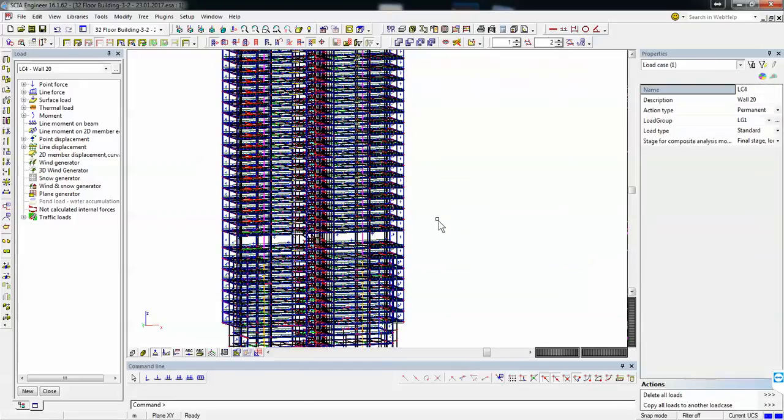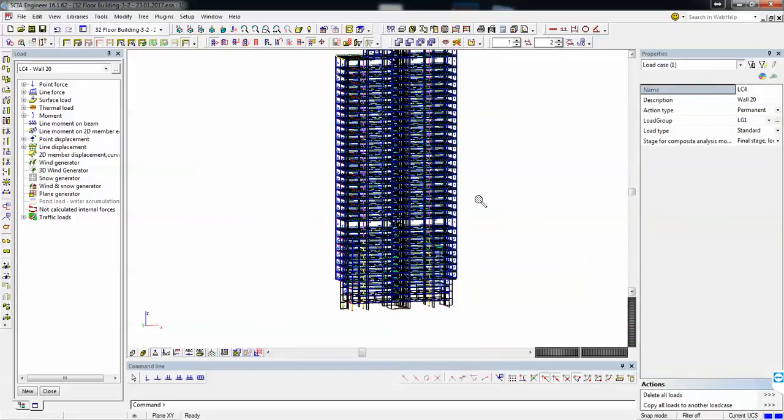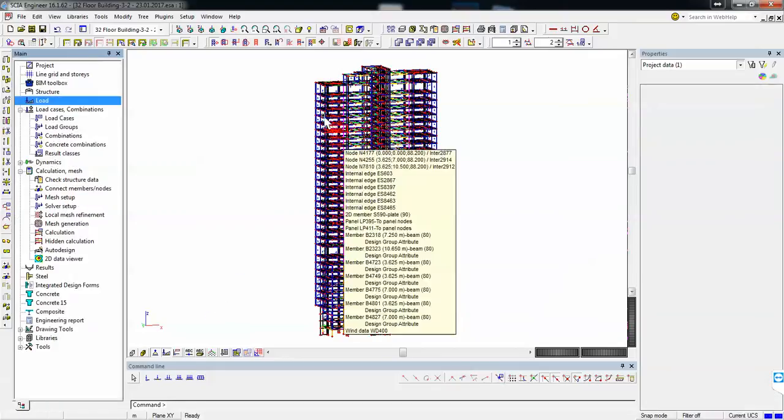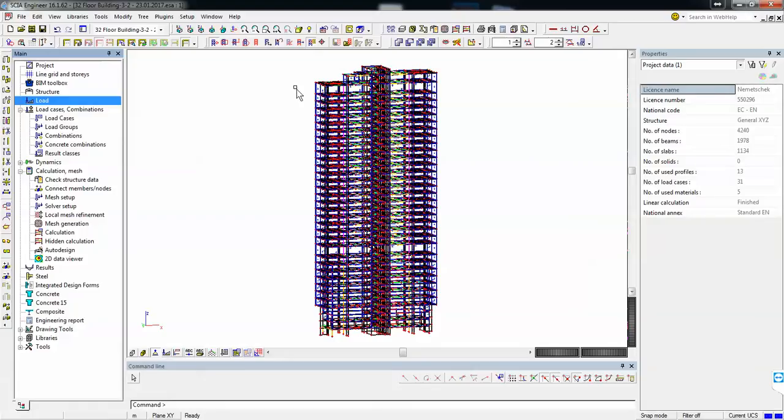Okay. So yes. Basically, if you consider we have all the loads, we can go to generate some combinations and then evaluate how the structure behaves, what are the displacements per level according to Eurocode, and if everything is okay, we can go and do an evaluation of the stability of the global structure. But I will need a break from this, so yes.